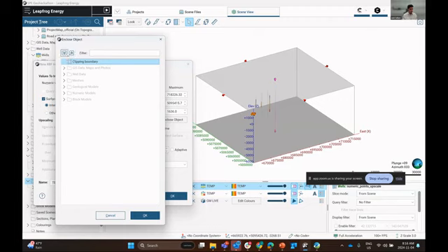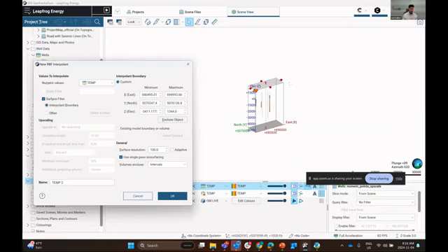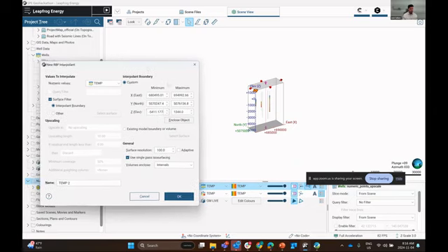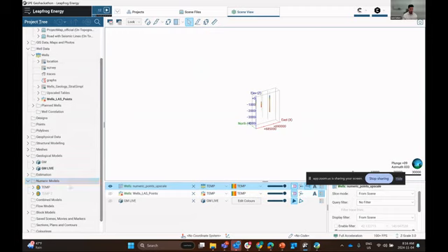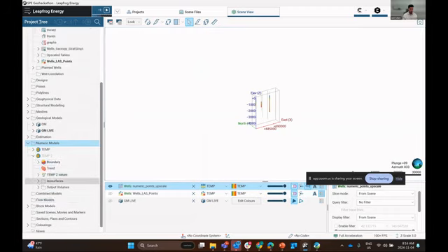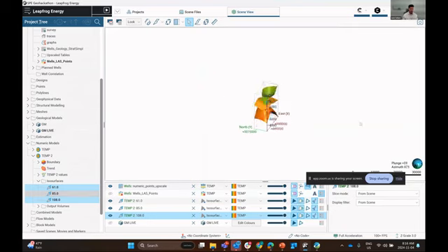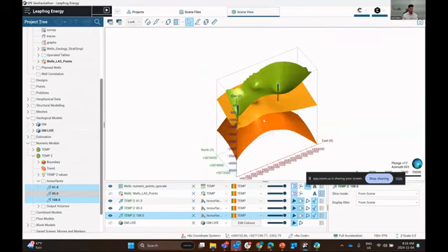You can also press this button right here or that one. I'm going to expand out my geologic model, go to GM Live, expand out boundary, and this is going to automatically adjust the boundary to the easting, northing, and elevation extents defined by my geologic model. So we'll press OK, and then in this temperature 2, we have some isosurfaces from statistically significant portions of our model.